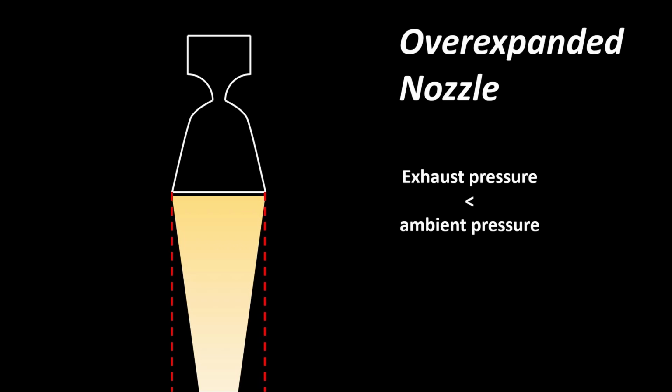meaning the ambient pressure is way higher than the pressure of the exhaust, pressing it inwards. It has no big influence on the efficiency of the engine, but on the thrust output, and poses a huge risk to the engine due to something called flow separation being able to occur. In other words, the expansion ratio of just 40:1 on a sea-level engine is far too low to operate efficiently in space. The solution for that is another variant of the Raptor engine, the Raptor Vacuum, or RVAC for short.